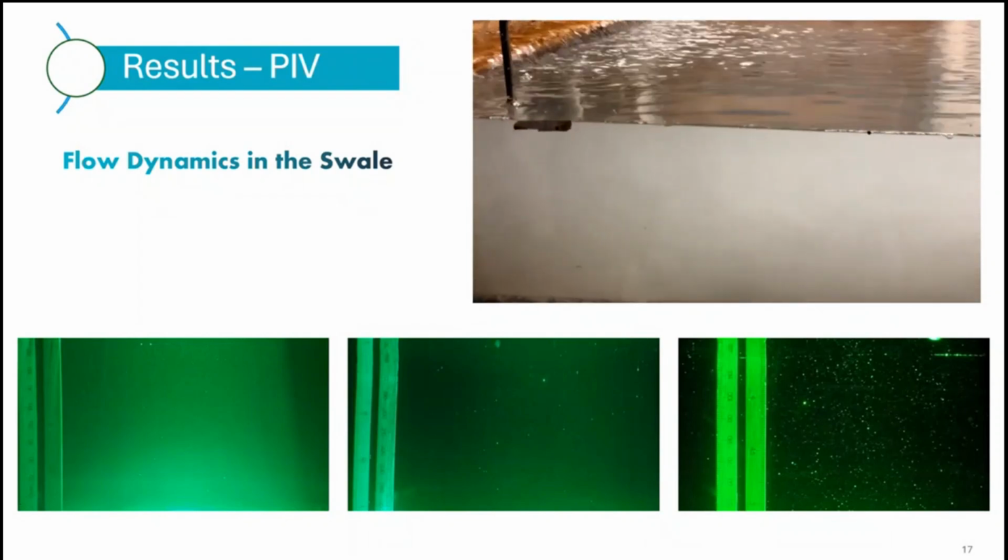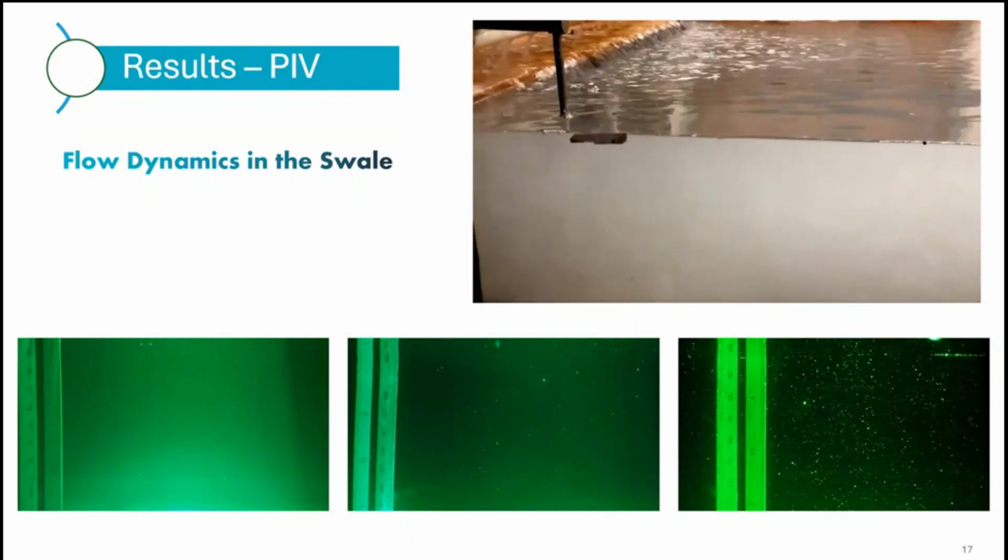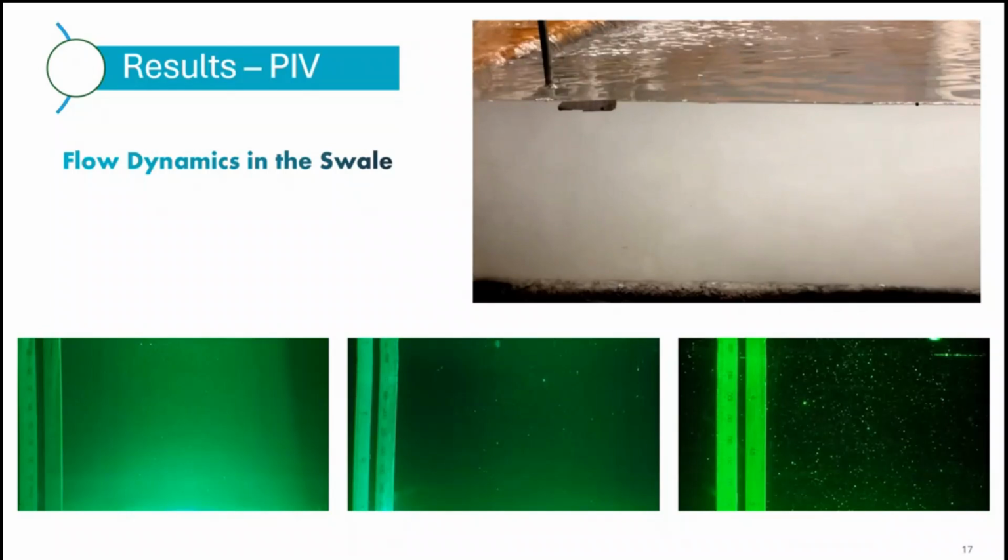It's a good thing, first of all, because you have more residence time, but at the same time it is increasing the total suspended solids at some places, and turbidity, as we saw, is not showing the reduction. So when we saw this video we captured by naked eye, we thought maybe we can have more investigation about the flow dynamics in the system.